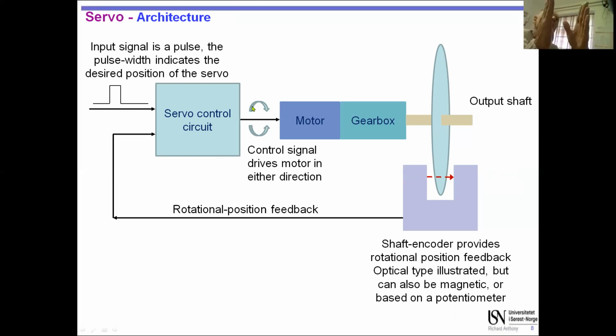Because if you're turning, the camera might go beyond where you tell it to, and it's going to come back. It may go slightly back, because maybe you moved the control stick too quickly, or maybe the wind blows the camera and the servo realizes it's gone too far and it comes back, because the servo will adjust itself all the time because of this loop. So that's another thing that's quite interesting about servos.